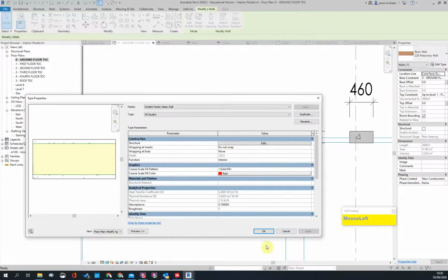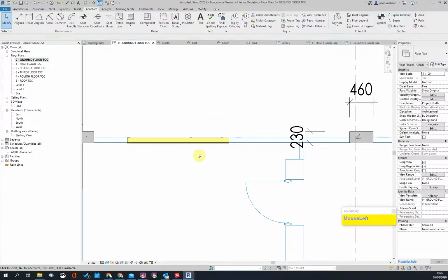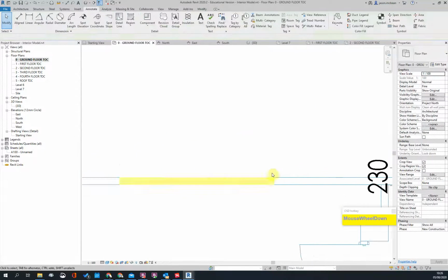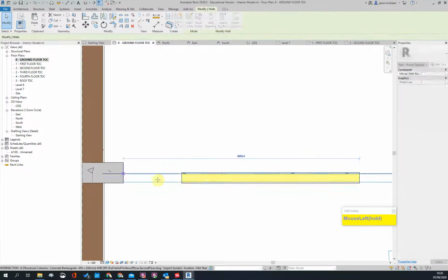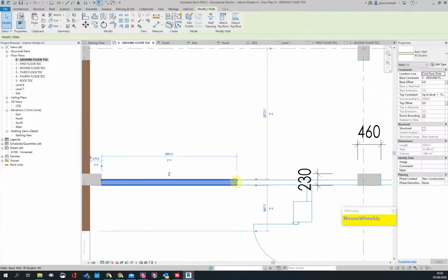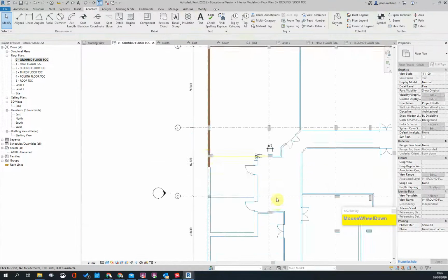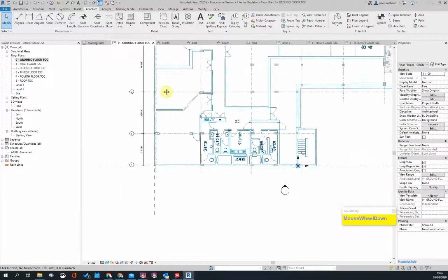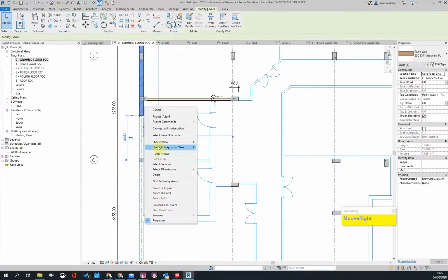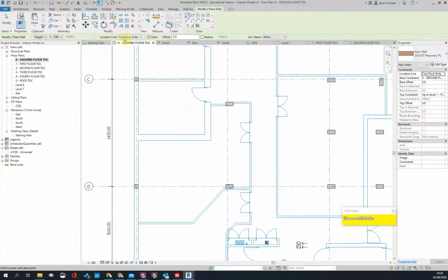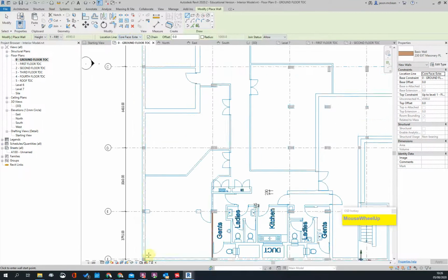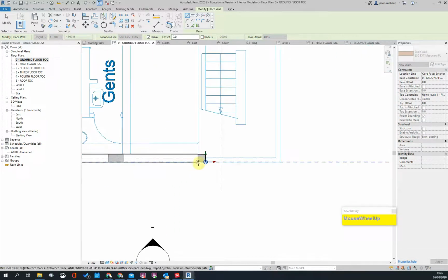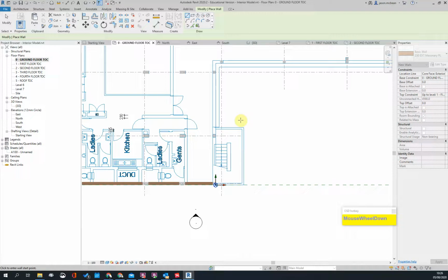Okay, so that's a stud wall in essence. Okay, same story, exterior core. Those are studs in essence. Yeah. All right, so the next thing I need to do, I'm going to establish all the exterior walls. So I'm going to grab this wall here, create similar. And remember, I want core exterior because I want to follow the exterior side of the wall. Spacebar to flip it.